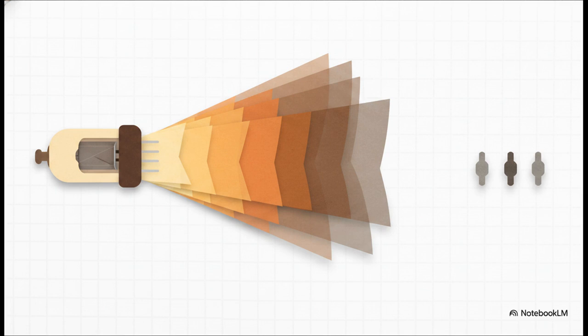On top of that, it had terrible fan-out. That means a single diode logic output could barely drive the inputs of other gates without the voltage drooping completely out of spec. Oh, and fundamentally, you couldn't even build an inverter with it. For complex computing, that is an absolute deal breaker.